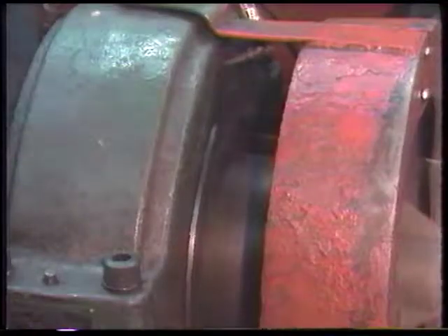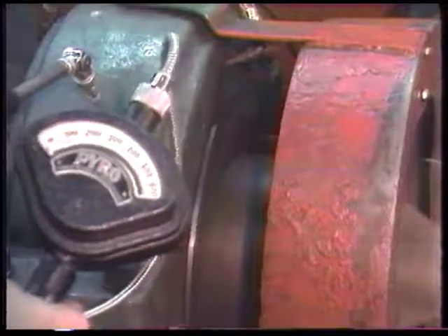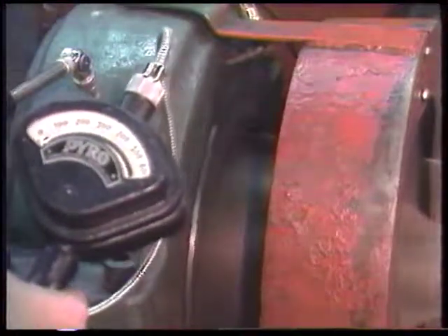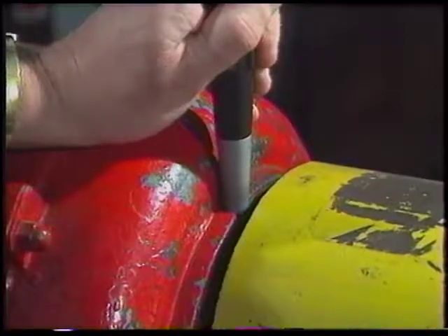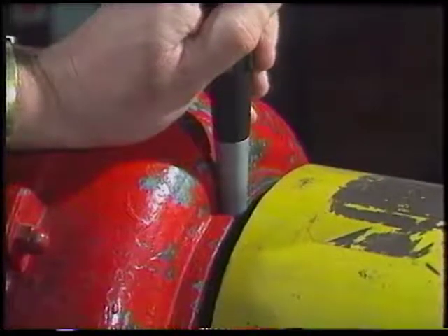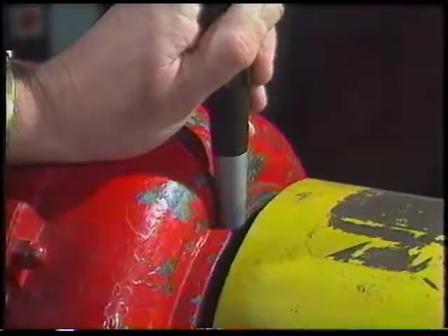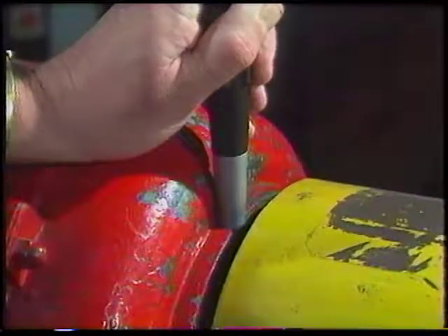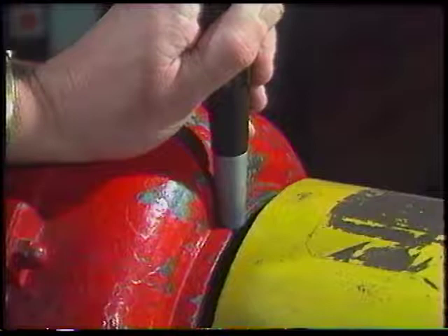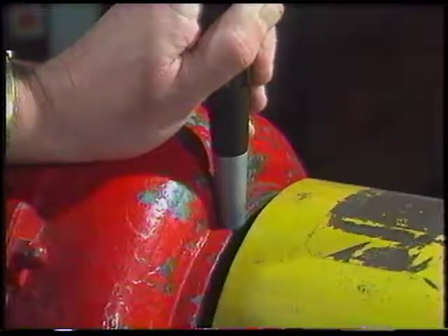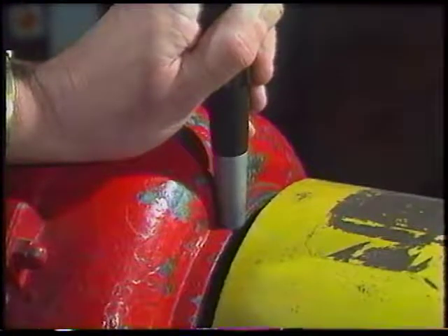After installation, it's always good practice to monitor the operation of a bearing when it is put back into regular service. When the machinery is started up, listen carefully to the bearing. There should be no abnormal noise. Keep an eye on the temperature. Usually it will rise at first, then slowly drop back to a normal running temperature after a few hours. Repeat these checks at regular intervals until you're satisfied that the bearing is operating correctly.